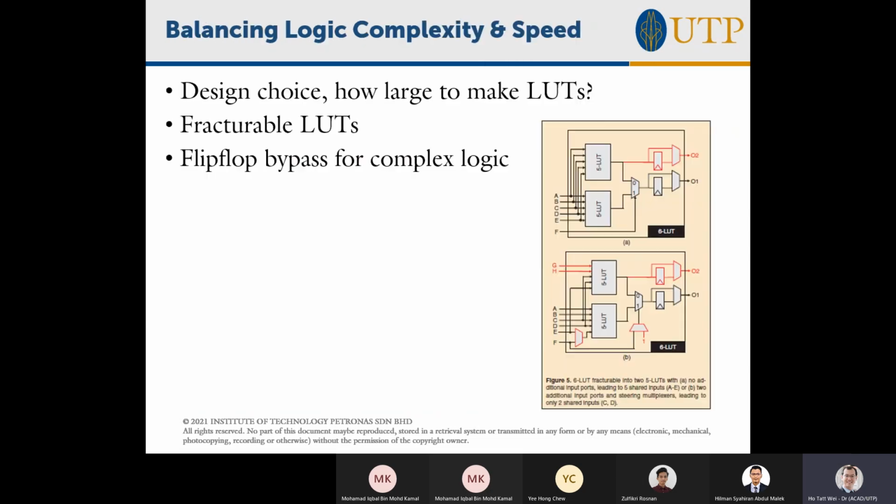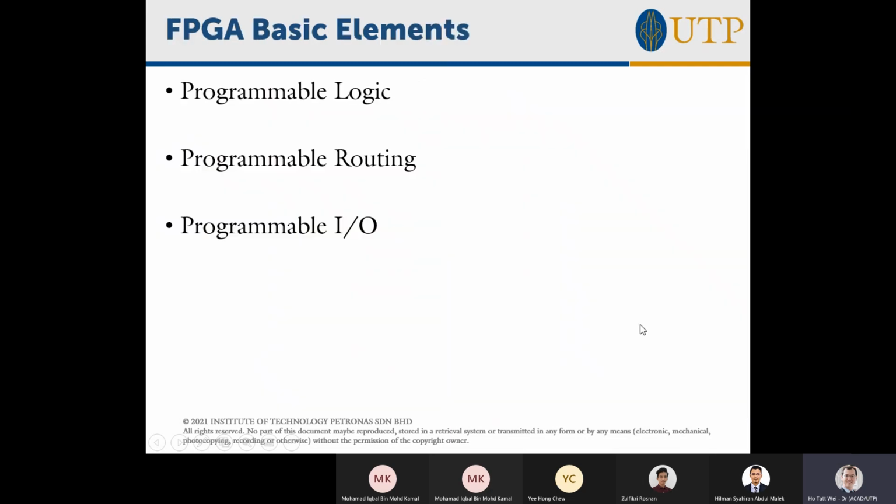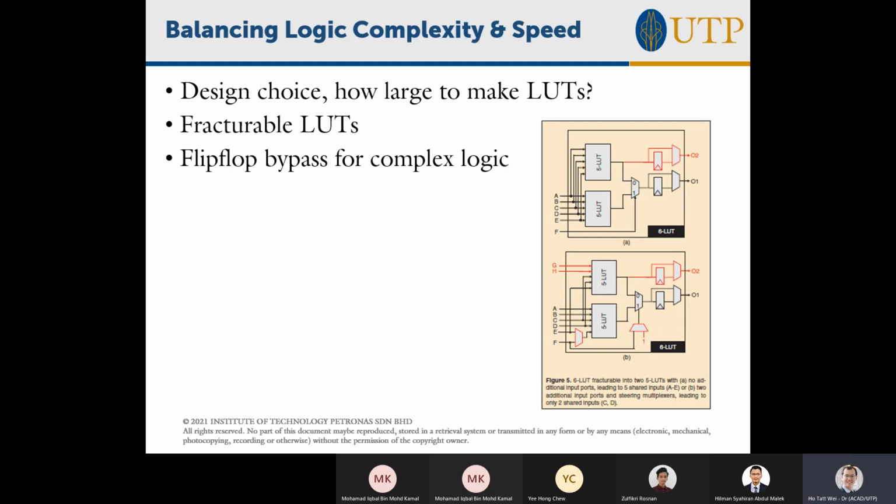Okay, so now we've talked very quickly about the basic programmable logic element. What does it look like? It's basically a bunch of SRAMs controlling some multiplexers, which can be connected either to VDD, ground, or to inputs. And outside of this K input lookup table, there's the option to tag on a flip-flop or not. Then you have a bunch of them connected together with some kind of feedback connection where you can configure this wiring via multiplexers again, and you can also configure the output via multiplexers, and this is a logic block. Okay, so we have covered the programmability of logic blocks.